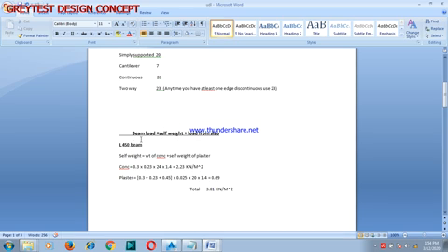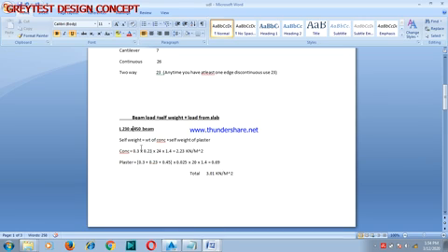Okay, for an L beam, when you have, for example, an L beam of 230 by 450, this is the self weight of concrete plus the self weight of plaster. This is the value you get whenever you have an L beam of 230 by 450. This is the value you should use.